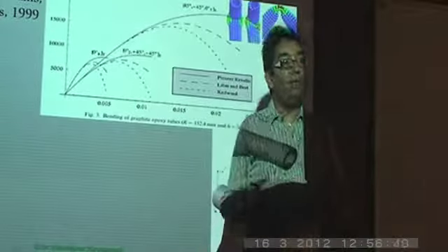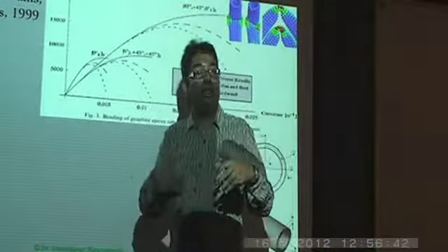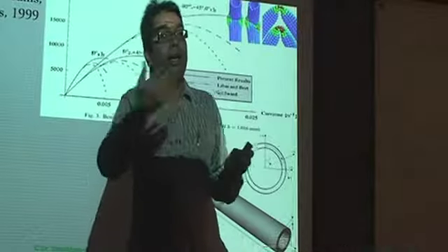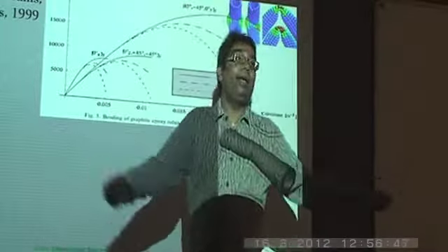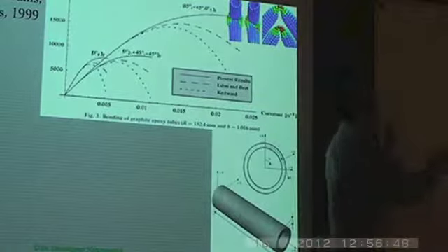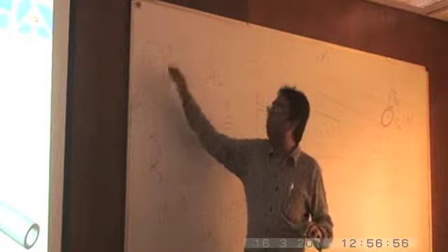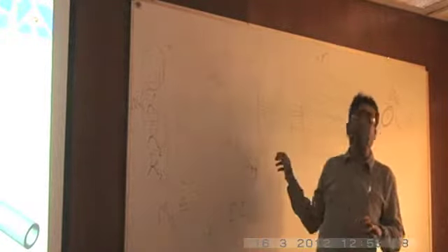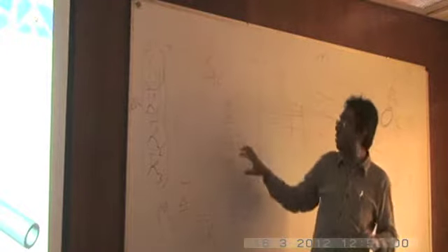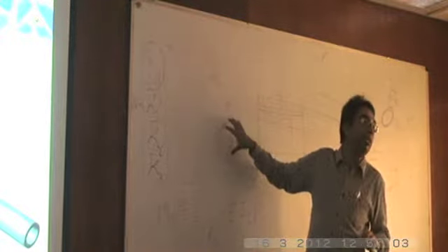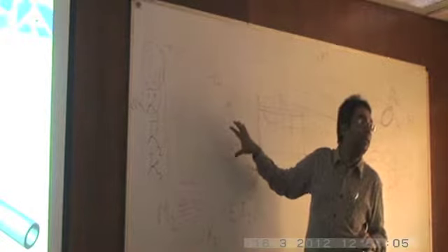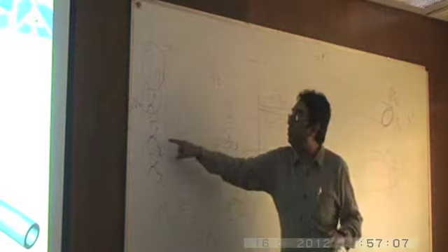Again, you integrate the 3D energy density over the cross-sectional area, then you get the energy per unit length. Once you do that, you end up with an equation like this, which is the 1D energy per unit length of the beam in terms of the 1D strains, and then you have a stiffness matrix. In that you can specifically look at this element, S33, which is the bending stiffness relating kappa 2 bar to M2, the bending moment about the X2 direction.